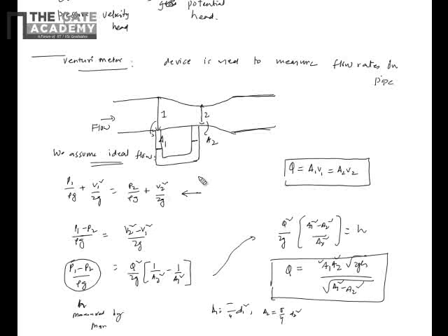So this you would have done in your lab, Venturi meter. So the only thing you need to know is A1, A2 and H. H is the manometer reading. From there get the H, which measures the pressure difference. A1, A2 already you know the diameters. So this is a very simple device to measure the volume flow rate, and it works on Bernoulli's equation. So just try to understand when Bernoulli's equation is valid.